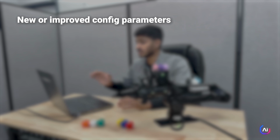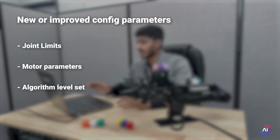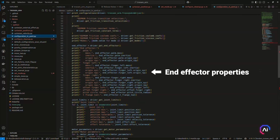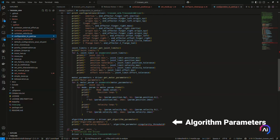We have also added and revised a number of configuration parameters. You now have more control over joint limits, motor parameters, algorithm level settings, end effector properties like pitch circle radius and tool flange transforms. A few outdated ones like continuity factor and Tmax factor have been removed for clarity. These changes give you fine-grained control over how the ARM behaves in different operating conditions.